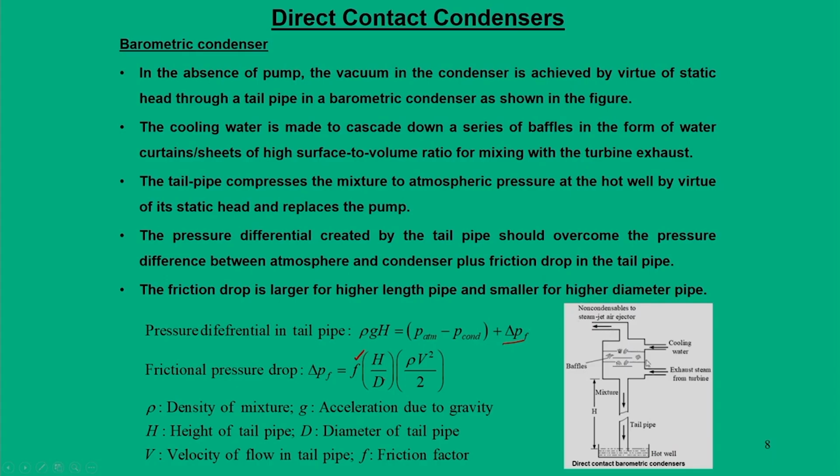So, for example, the water which is condensed goes out through this tailpipe, and whatever non-condensables there are have to be taken back through a steam jet air ejector system. So, these are what we call unwanted parts as far as the condenser requirement is concerned.